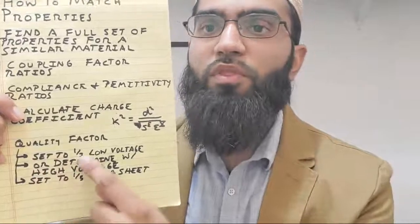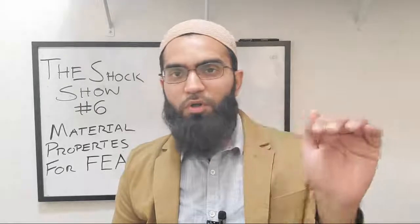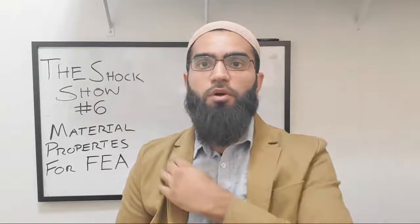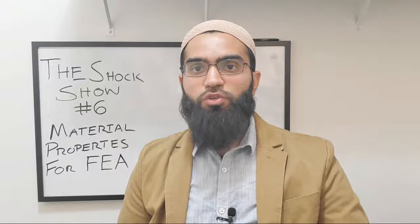You put 1/3 of the low voltage quality factor. The reason is because when you excite your piezo with anything more than like a volt or a small excitation, the quality factor is going to drop really fast, and that's because losses by domain wall motion in piezoelectric ceramics, especially PZT, are extremely susceptible.